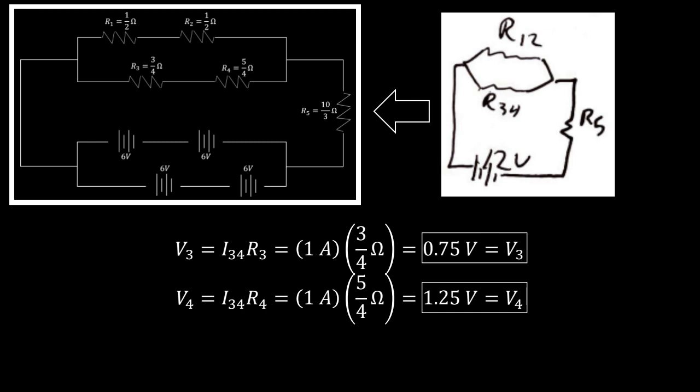And if we collapse this into one single path, that would be overall 2 volts between our first branch point and the next. And what we found was across R5 was 10 volts. Therefore, 2 plus 10 gets us back to the 12-volt battery supply. So things in series, the voltages should add up eventually back to our battery supply if we collapse everything onto a single path. Things in parallel, the voltage across one path should equal the voltage drop across the other path,